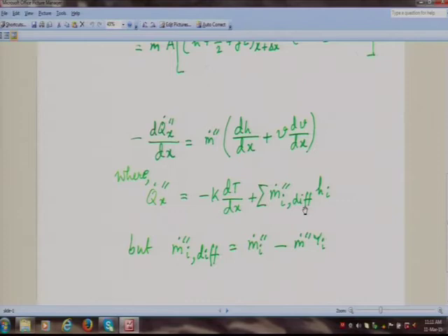Okay. Again, what is the purpose of doing all this? Remember that Mallard and Le Chatelier had given a simple thermal theory for flame propagation, but there we got S L as a proportionality, S L proportional to the square root of alpha into reaction rate. This is what we had done in the last class, lecture 21. Now, we are not happy with that, because we want an expression for S L, S L equal to something which will allow us to calculate S L and, for various mixtures, have some good estimates of what S L will be like.